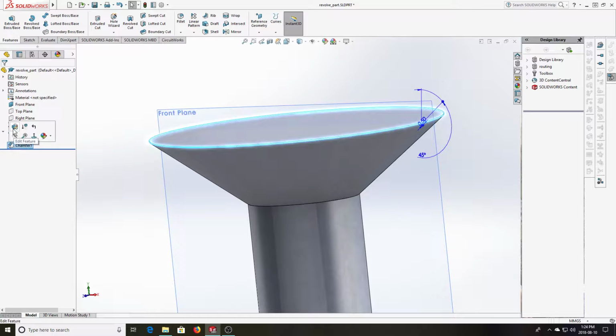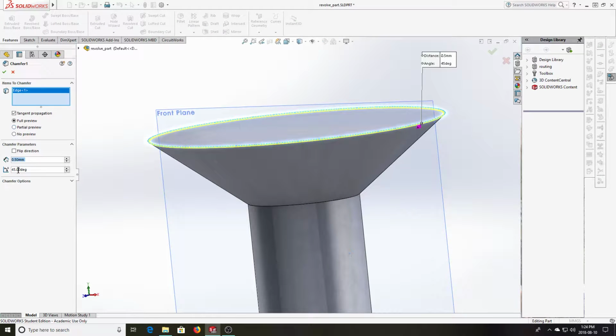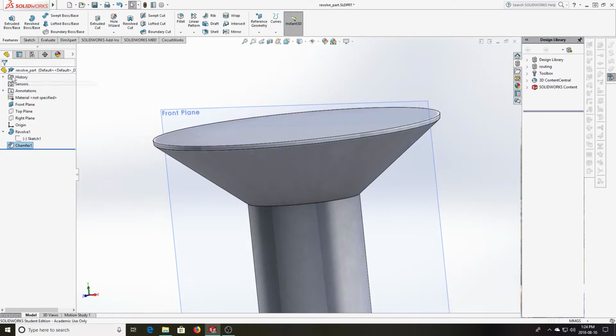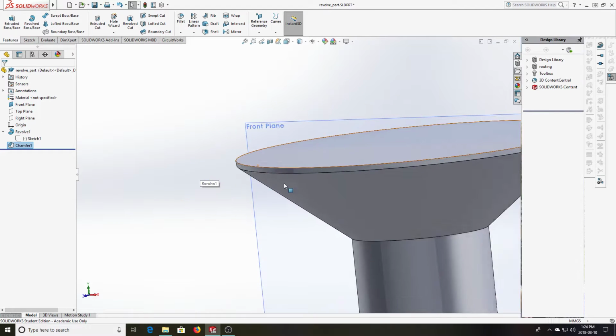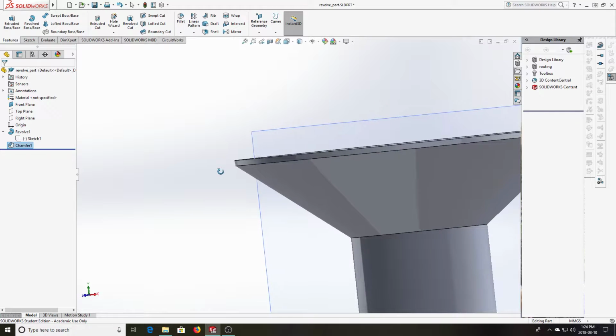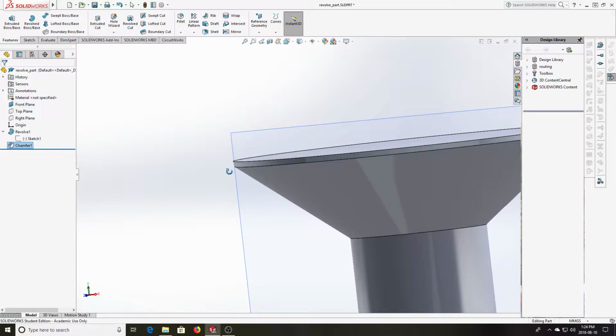If I go back to the chamfer, I can edit anything by just re-clicking on it, and if I make that chamfer dimension, I can just change the number here and make it 2 millimeters. Well, that clearly looks different again, and it just happens that the angle that it's chamfered at is 45 degrees between the bisecting angle of the two faces. SolidWorks calculates that somehow.